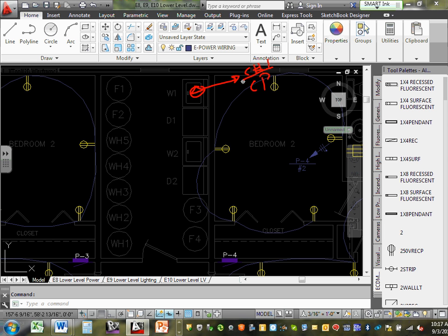This is for washing machine number 1. Washing machine number 2 will have something similar, circuit number 2, CP, common panel. If I were you, I would make it circuit number 1 and 3, so each one of these washing machines is going to have a dedicated 1 circuit. Can I have thumbs up, Chad? We know why 1 circuit says 120.